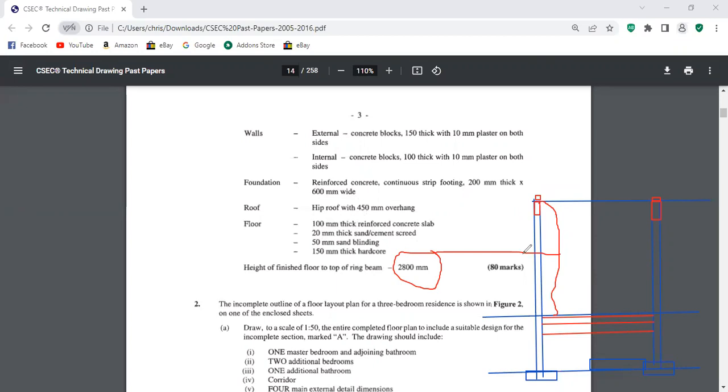And how do we draw the overhang? If we're using AutoCAD, first I will draw a line at 30 degrees. In some cases, they will not give you the angle for the rafter. If they don't give you an angle for the rafter, what do they use? The dimension is 150 by 50, but what angle would you use? 30 degrees typical, yes. So what I would do, I would draw my rafter.